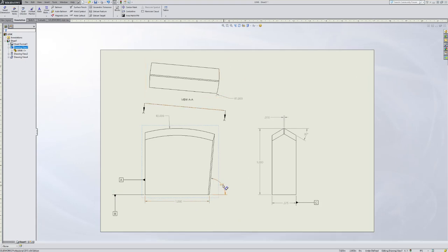So if we changed this degree from 85 to say 87 or whatever it was that we wanted it to be, that reference sketch is always going to follow it, so this auxiliary view will follow it as well. If we just did the auxiliary view inside of our drawing here, we'd have to go back and reassociate that each time, but that's not what I want to do.